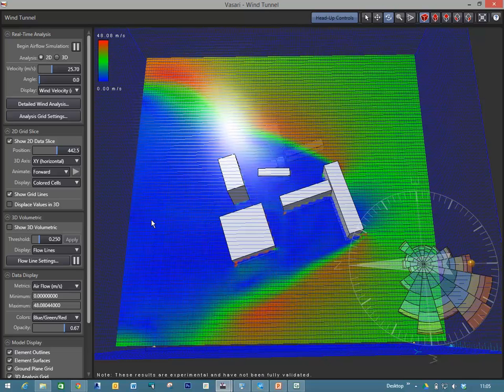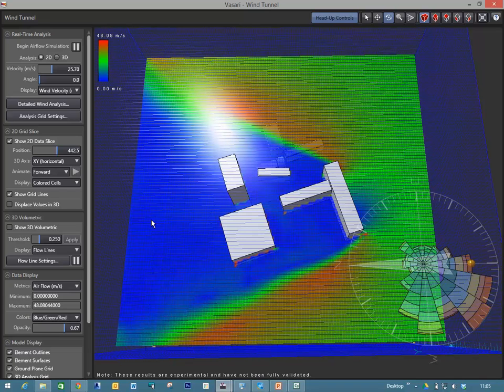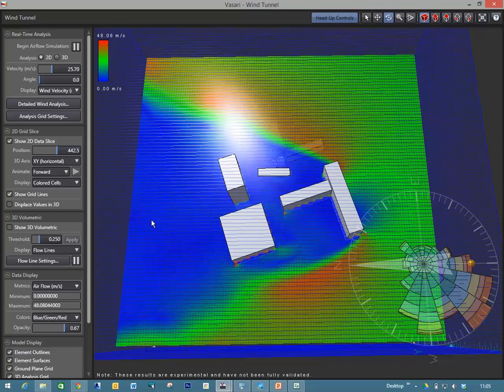The thing to avoid with them is to try and do very, very complex analysis. So, for example, in the past I had a student who was trying to use Vasari to simulate wind flow through a building, and the software's not really designed for that. It's designed for a more urban scale flow around buildings. Okay. Right. Any questions before we take a break?